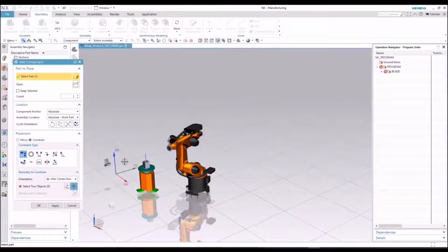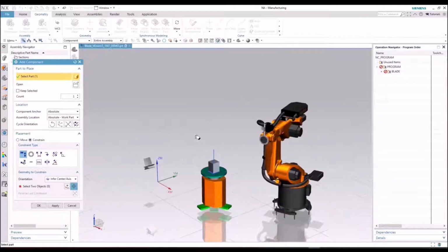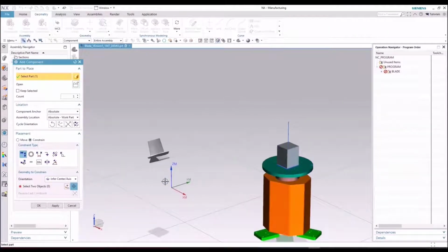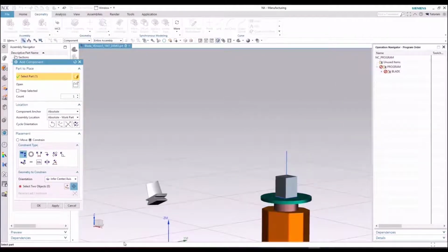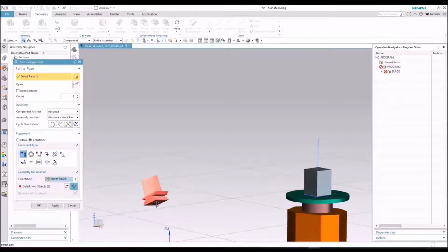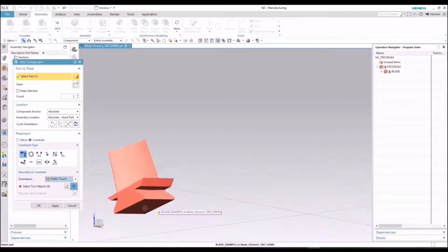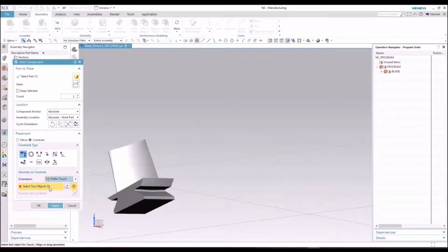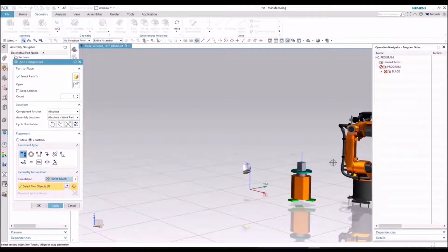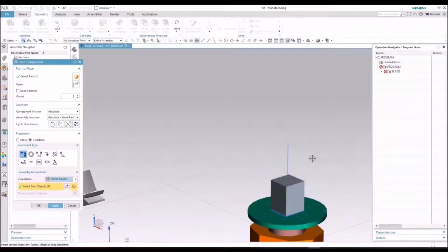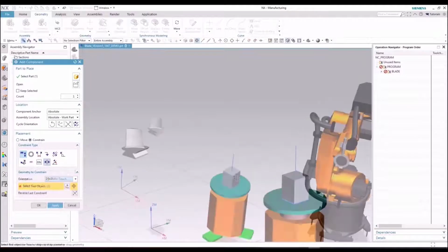In our case, we use a KUKA KR60 6-axis industry robot combined with an external axis, a positioner with a rotary plate. After the CAD model of a workpiece has been added to the CAM session, it is placed in the preferred position by applying suitable constraints. Thus, turbine plate and its support are stacked in the center of the positioner table.